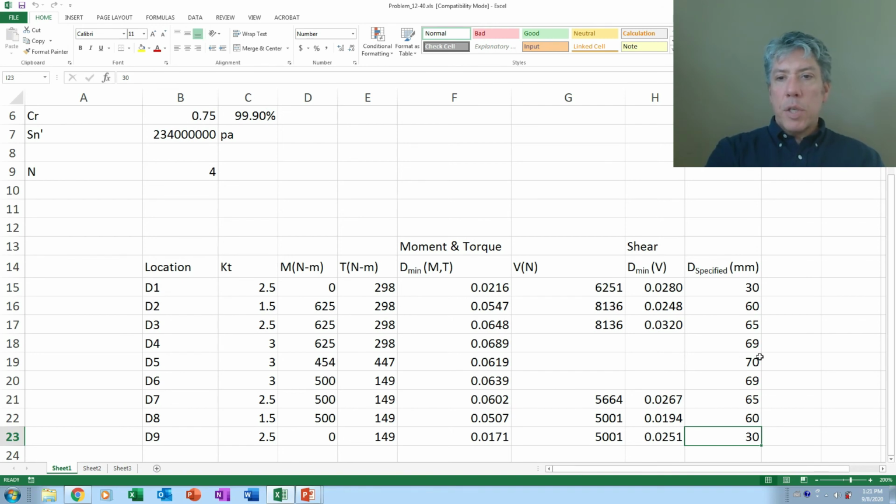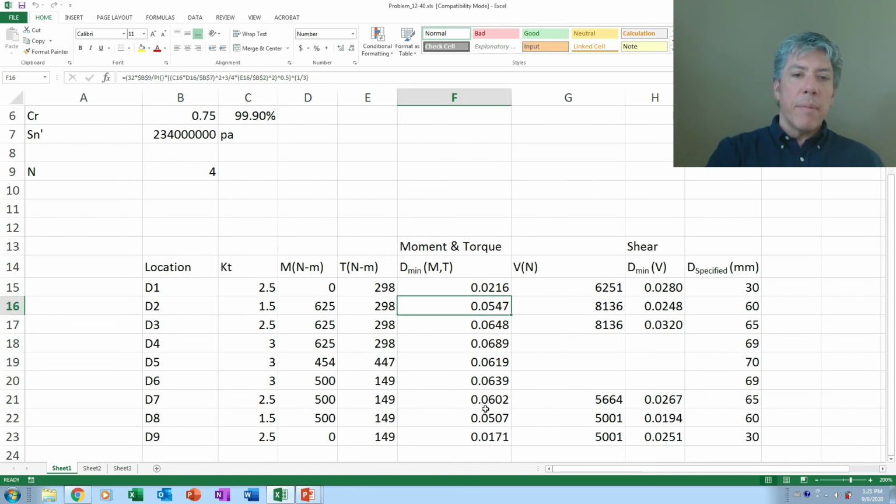And so you notice that the shaft ends up being symmetrical, and I really prefer to design that way if possible, because if it's something where the loads are, okay, the moment's higher on one side of the shaft than the other, the torque's higher on one side than the other, but you notice the diameters don't really come out that much difference. We got 55 millimeters here and 50 millimeters here roughly. That's not that much material, right?